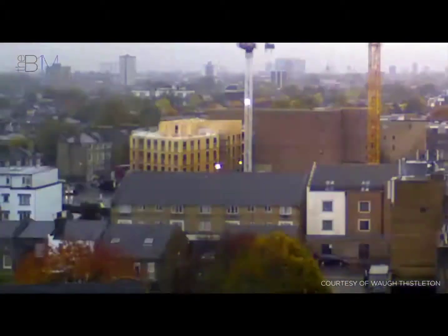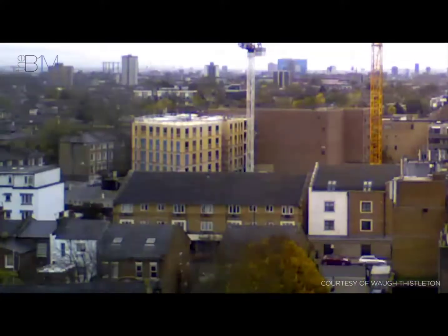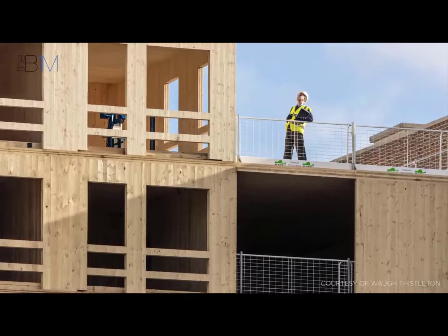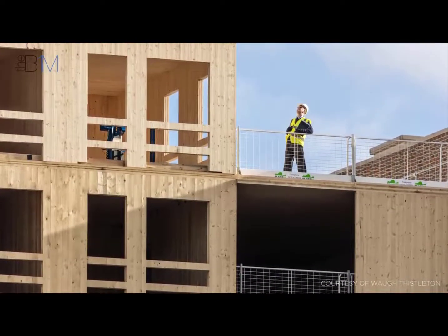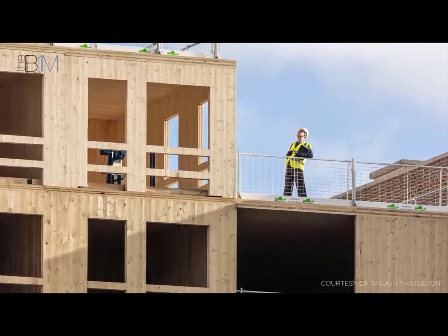The prefabricated panels can be delivered to site as they're needed, making this construction method ideal for schemes with limited on-site storage capacity. They are then lifted into place using pre-installed lifting straps and rapidly assembled, greatly reducing construction time and therefore cost. As the timber used is kiln dried, CLT should not shrink or warp when on site.